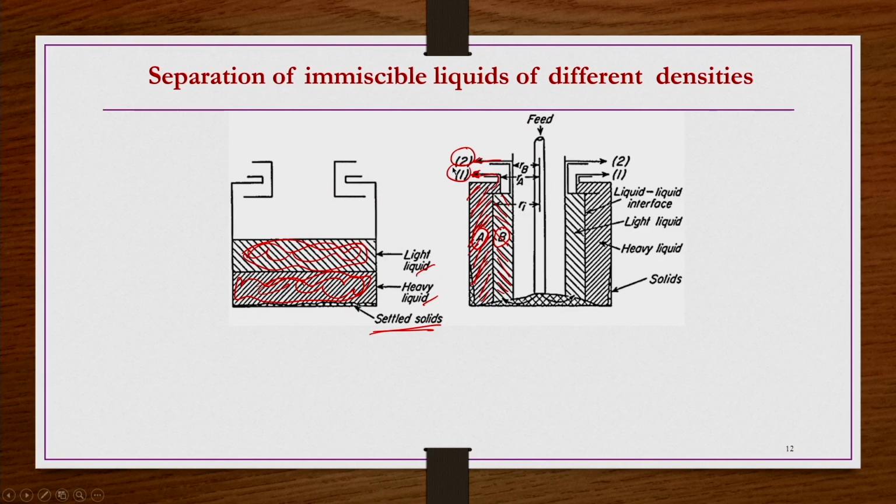So, here the notations are again the same. R2 is the radius of the bowl, and the height of the bowl is B, let us say, right. Now, RA and RB are the corresponding radii of the outlets for heavy liquid collection and light liquid collection respectively. Now, because the feed is continuously coming in and you can continuously take out these liquids, you do this process continuously, right.